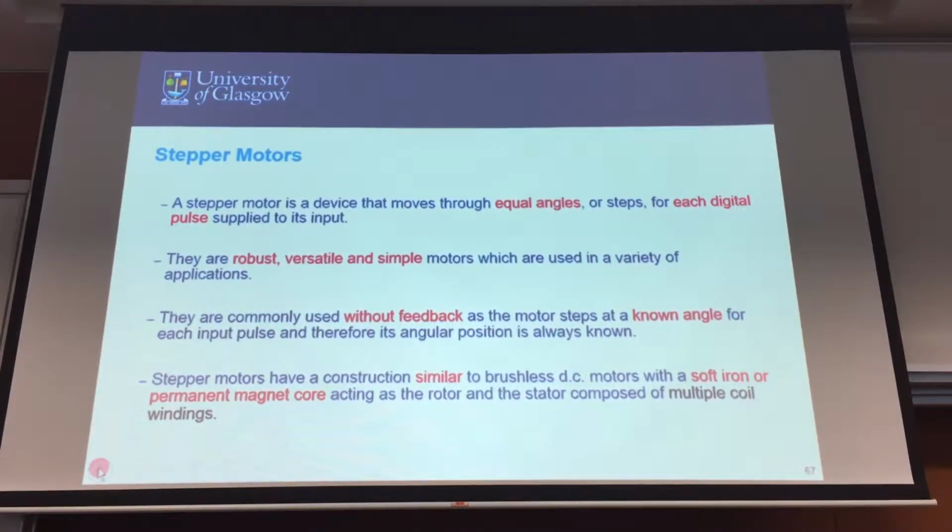And if after that you say, I got that position and want it to stay in place with the load that's attached to it, then that's making use of another set of knowledge that we were talking about, hydraulics. Because hydraulics can make sure that after it turns, it stays in that position without you applying any brake. But if you want to use a stepper motor, move to that position and also want it to stay in that position, lock in that position, then in any electric motor you have to have a brake mechanism, right? Because it cannot brake in place.